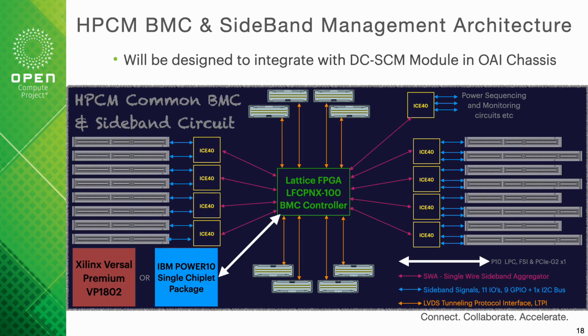And finally, a critical part of our project here is the board management controller and sideband management. There's an awful lot of that in there, and we want these modules to boot independently, but we also want them to be designed to integrate in with the DC-SCM security module infrastructure that will be housed in the OAI chassis. And so here Lattice are contributing some of the serial tunneling protocols that will allow for an efficient implementation in the design, and they're helping us with this.